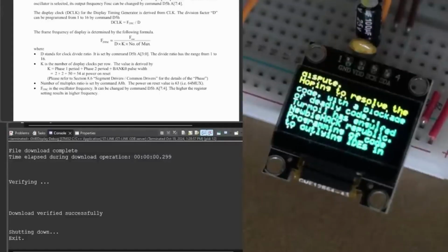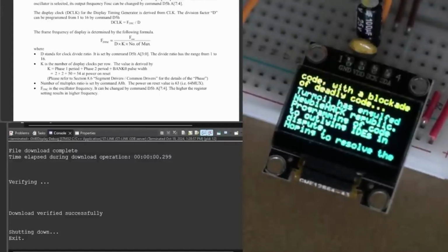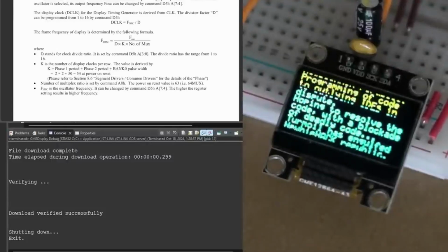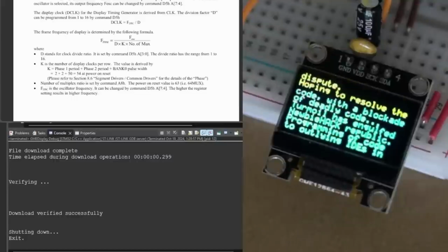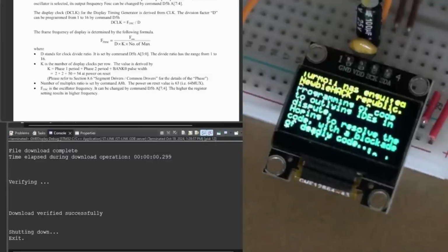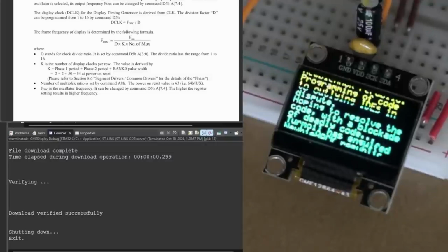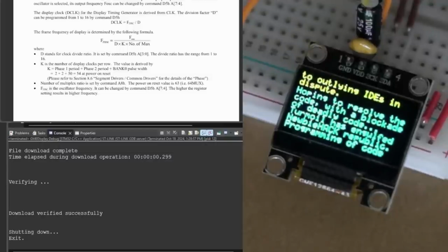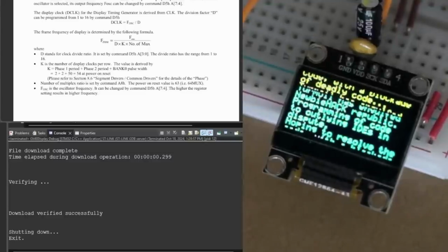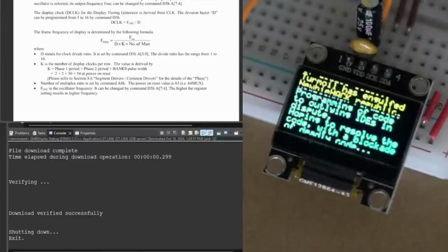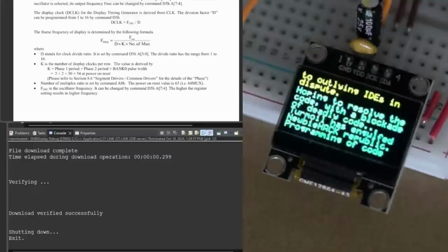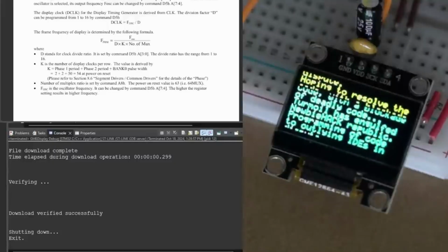Thanks. Let's read this. So this is the internal oscillator divider. This is the infamous MUX. This module is an on-chip low-power RC oscillator circuit. So it's a standard RC, it's not crystal-based. In other words, the operation clock CLK can be generated either from the internal oscillator or the external source CL pin. We're using the internal oscillator, I'm assuming.